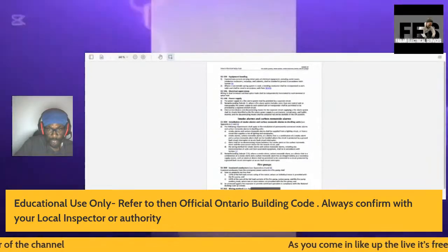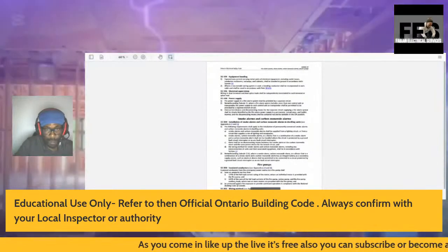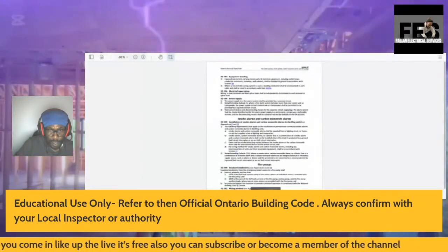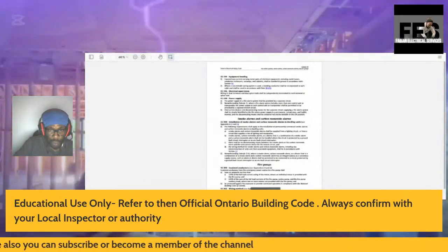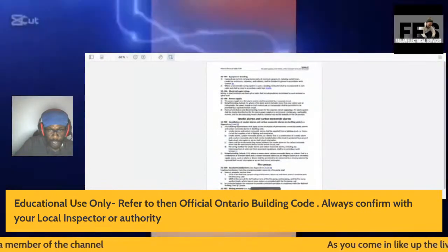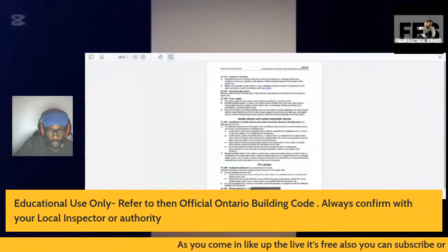Again, the nuisance is going to trigger the smoke alarm, and that's probably why they're saying not to install it. I've always pulled my lighting circuit to the smoke detector, so I don't have an issue with this rule here.